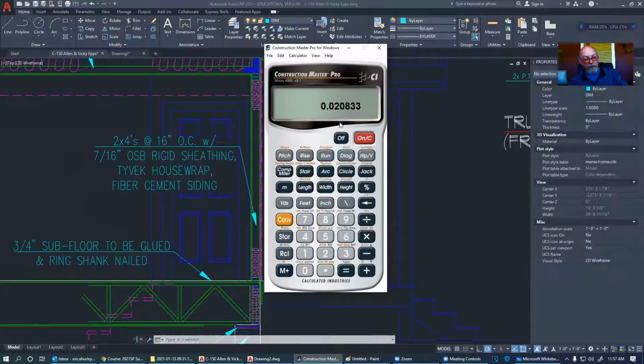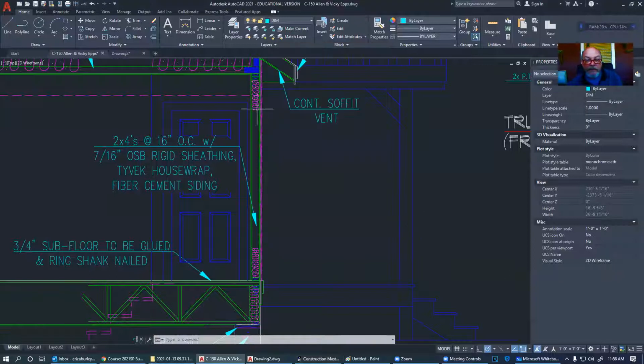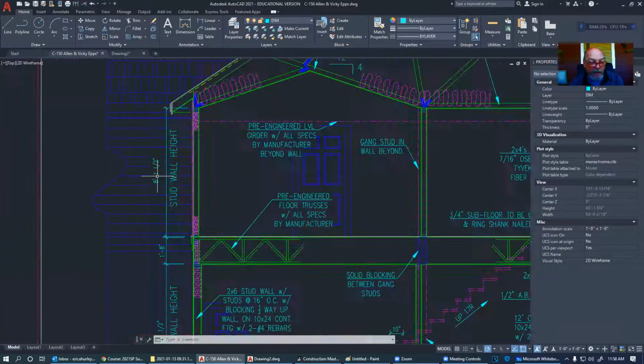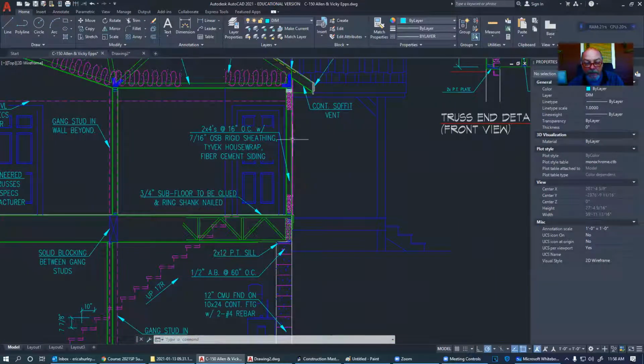So let's say, for instance, I could still do this on an 8.5 by 11 sheet of paper. If I wanted to do a 1 inch scale, 1 divided by 12 is going to be 0.0833333, times 93 inches. I could do 7 3/4 of an inch here, and that would be the height of a stud. So you can use your ruler to draw out the height of the stud. Now these are not 98 inch, yeah, they are too. 93 inch studs through here will give you that.